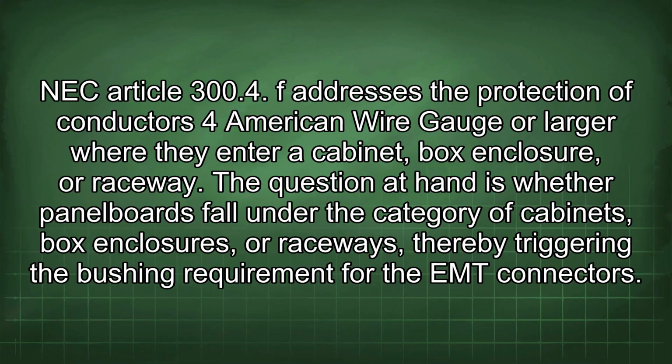NEC Article 300.4(F) addresses the protection of conductors for 4 American wire gauge or larger where they enter a cabinet, box, enclosure, or raceway. The question at hand is whether panelboards fall under the category of cabinets, box enclosures, or raceways, thereby triggering the bushing requirement for the EMT connectors.